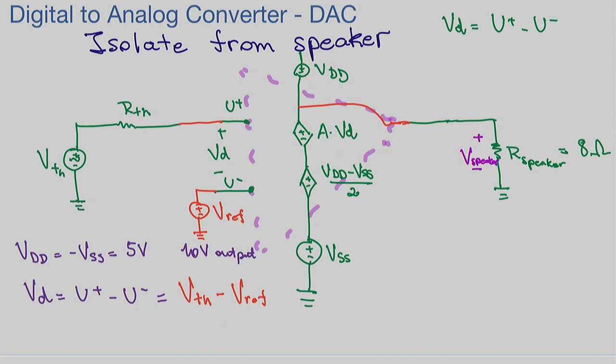When I designed this, when I started, I had the op-amp like this. Let me erase that, like this. So what are those connectors there? What are those leads from the op-amp? U plus and U minus. Which elements are they? How could you model that element? Open circuit. An open circuit, thank you.